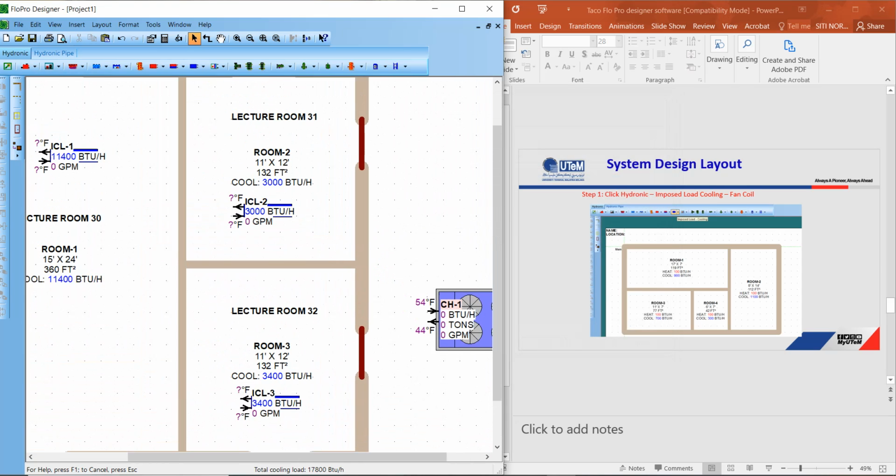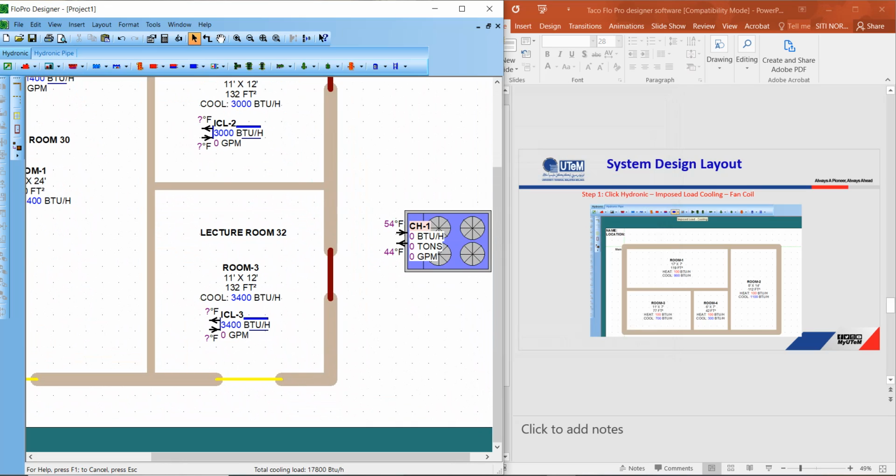Do the piping connection. Once the piping connection is done completely, complete means there is a supply and a return. Just connect it. This one is hydronic out. This CHWS, chill water supply, will appear like this if your connection is correct, with the arrow coming in.